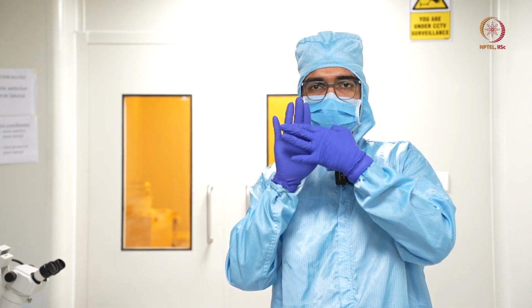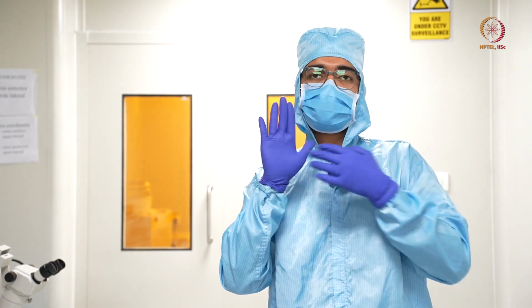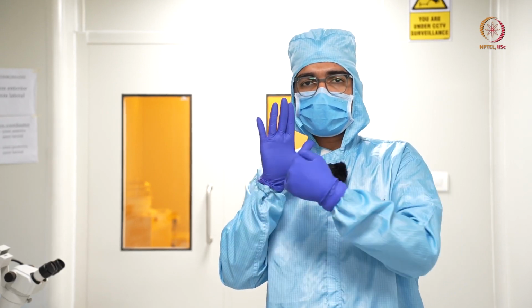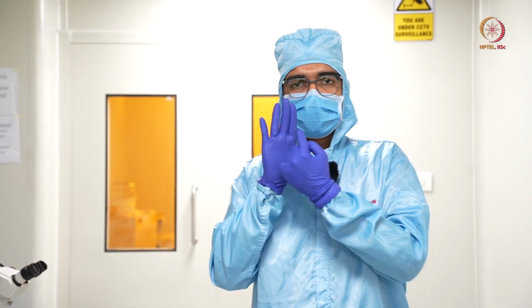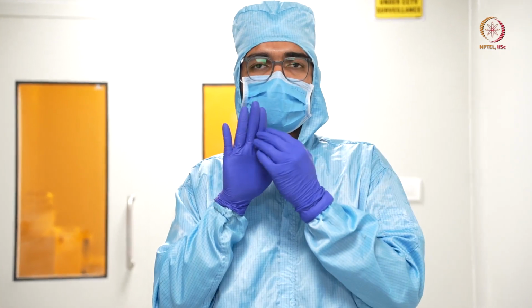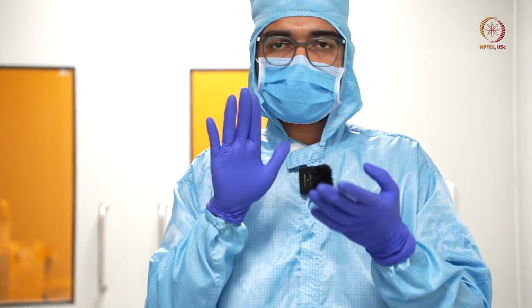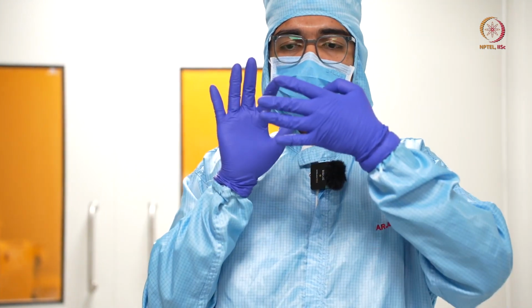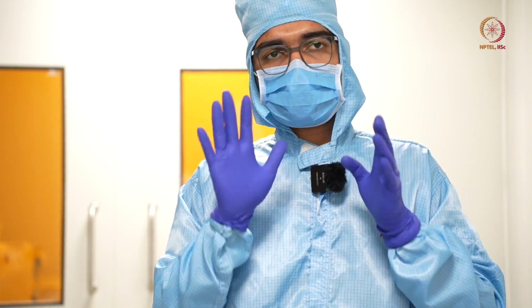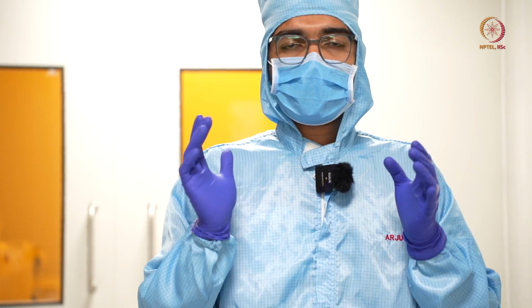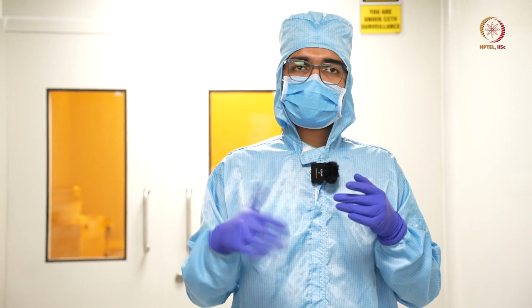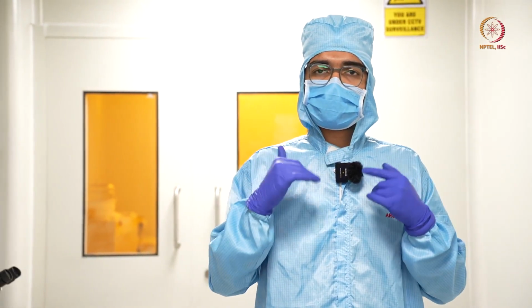Then if the light passes through here and falls on the substrate, if it's a positive photoresist, wherever light has fallen, it will become a soft region. When I say it's a soft region, what it means is that later on during a process named development, the photoresist which was exposed to light will go away, or it will get removed. Now if it is a negative photoresist, wherever light has fallen will become strong and it stays there. So these are two different types of photoresist that we will be using. Now for our specific use case, we will be using a positive photoresist. That means if light falls, it will get removed, or it will become soft.